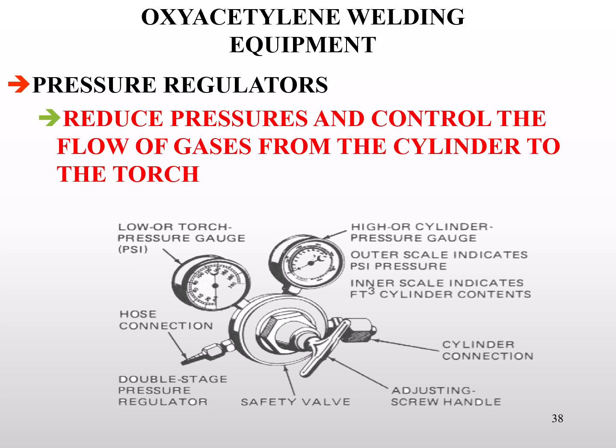There's a video that accompanies this PowerPoint in the module further explaining this. But this is a dual stage regulator because it has two gauges. The gauge closest to the bottle is your high pressure gauge. The gauge furthest away, closest to your hose connection, is your low pressure or work pressure gauge. We can set the work pressure by turning the handle in and out on the regulator for the desired PSI.